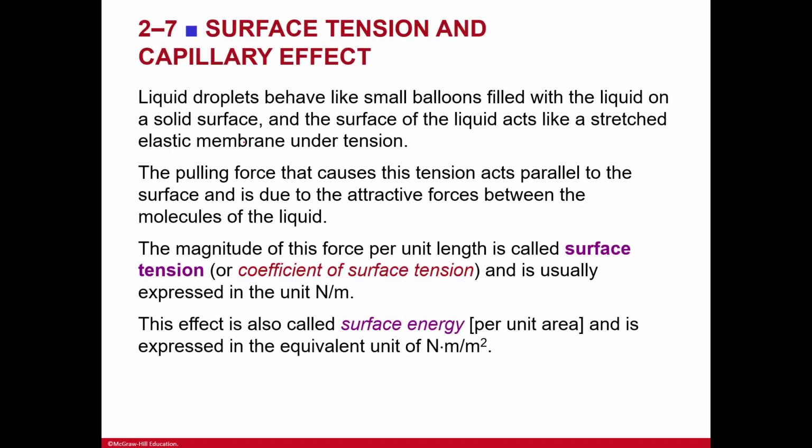So surface tension and capillary effects, we talked about this a little bit. So liquid droplets behave like small balloons filled with the liquid on a solid surface. And the surface of a liquid acts as a stretched elastic membrane under tension, kind of like a very, very tiny balloon. The pulling force that causes this tension acts parallel to the surface and is due to the attractive forces between the molecules of the liquid.